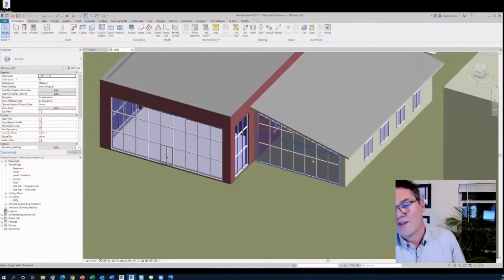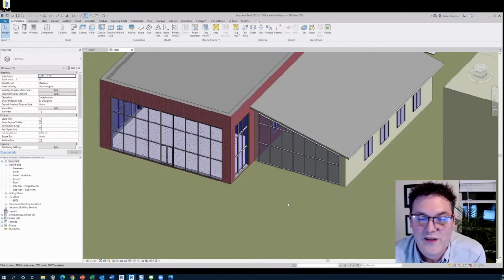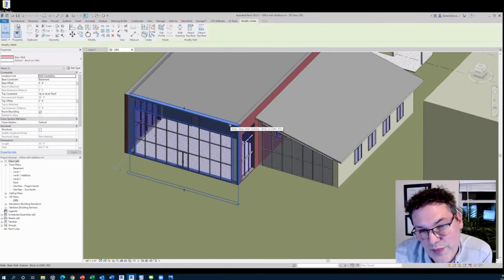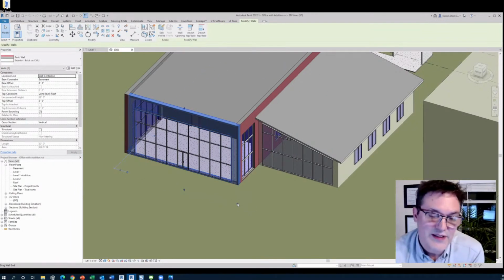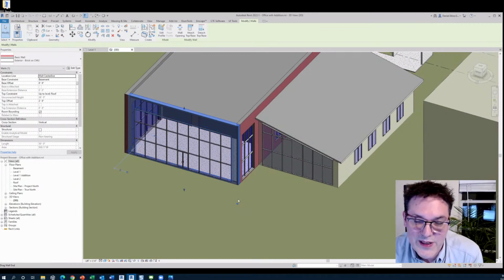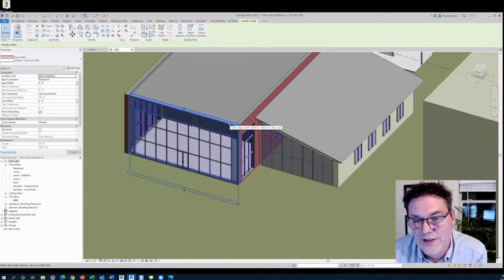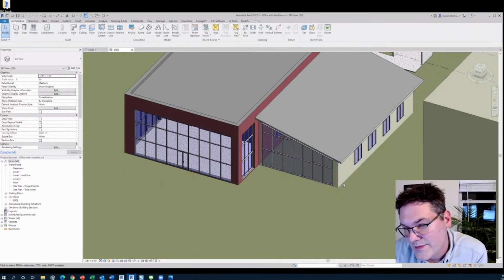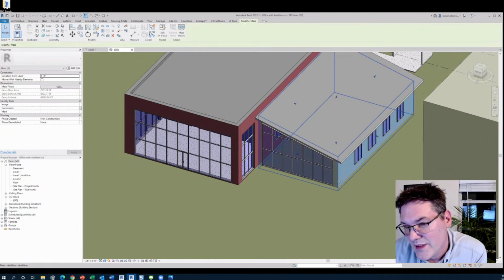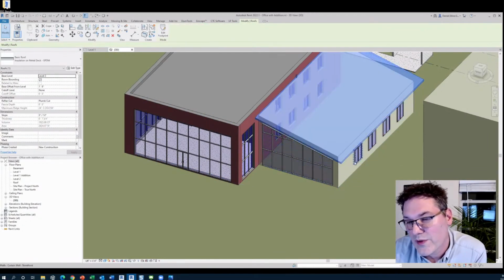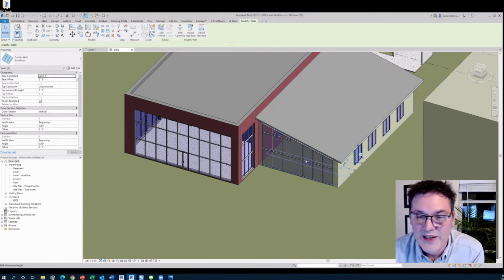That's great. So this shows a lot of the bells and whistles of a model, the conversion process. Here's a wall that goes down and has a basement, but maybe this is a tilt-up precast wall that goes from top of footing up to a parapet that's a certain amount above the wall. Here's a mass element, and it has some actual windows and an actual Revit roof superimposed on the mass.